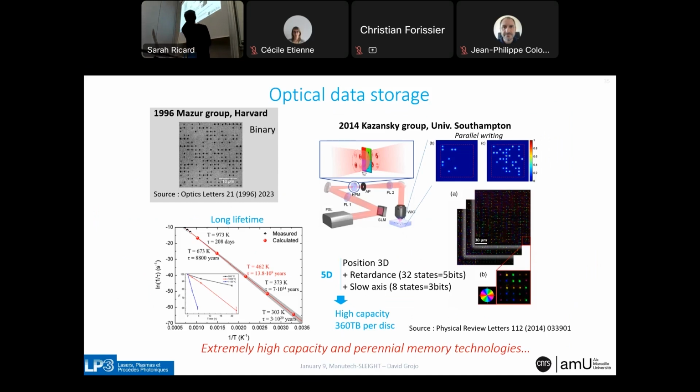And what they show there, for instance, is color plots. Each color corresponds to a birefringence level. It's a given piece of information. You see, we have different planes. It's a reading at different planes inside the glass, and we can read the information in this 3D structure. They read the information optically with a standard birefringence microscope.